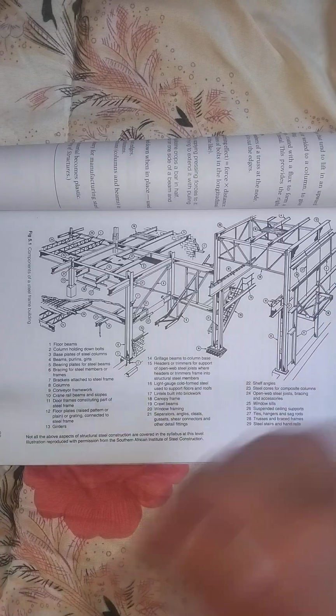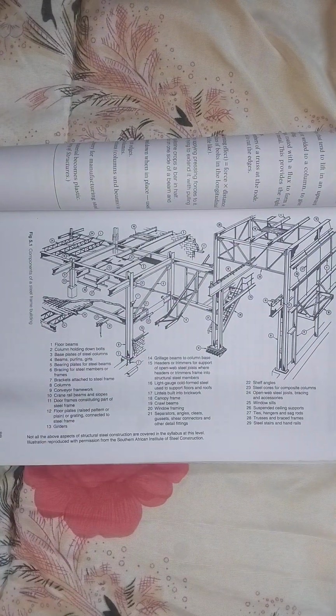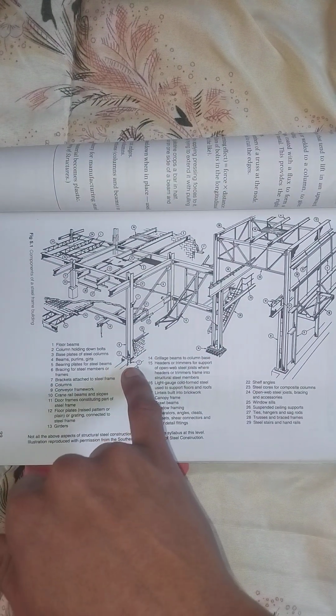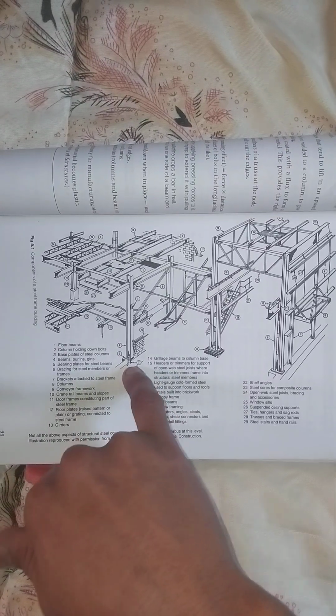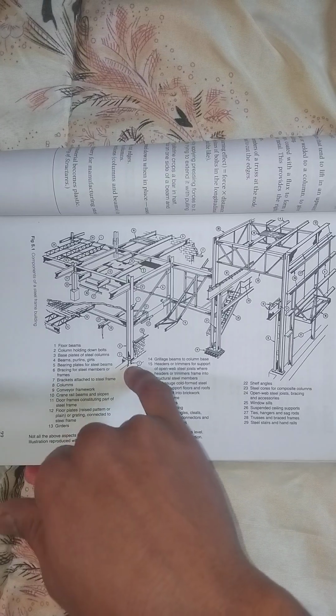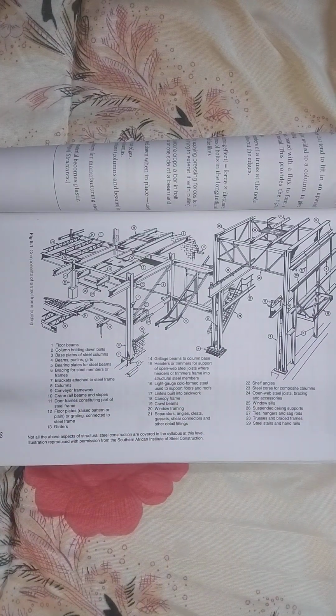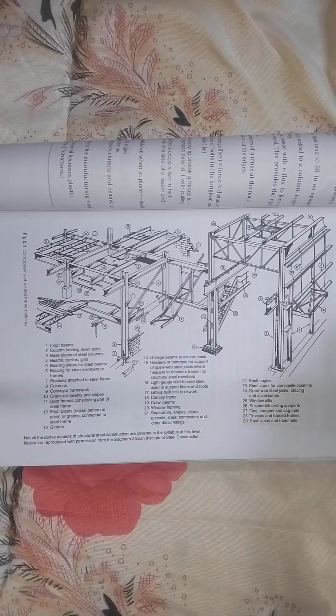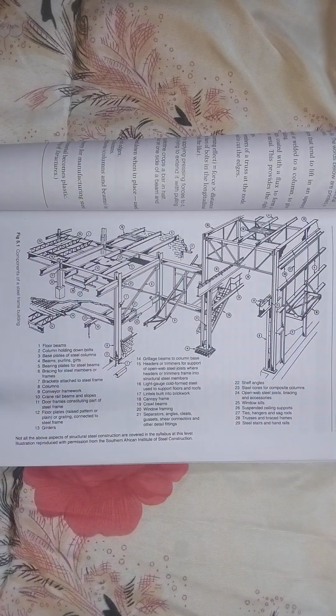And then you have your column holding down bolts. Basically it's like a U bolt or a J bolt, but I'm assuming it's supposed to be somewhere at the lower points of your columns. Okay, there, number two. That one is bent into an L shape, but usually they use U bolts, because then you have a resultant force, and usually your resultant force is your biggest resistant force. That's one of the advantages of using U bolts instead of J bolts or L bolts, whatever you want to call them, looking like L shapes.